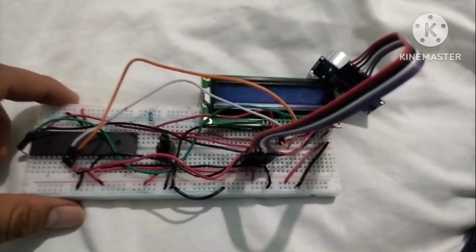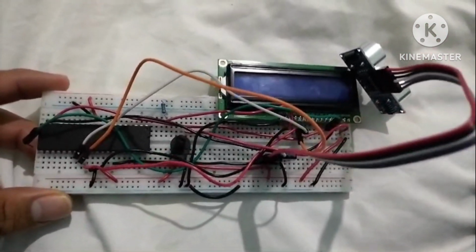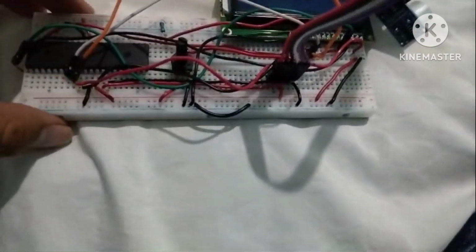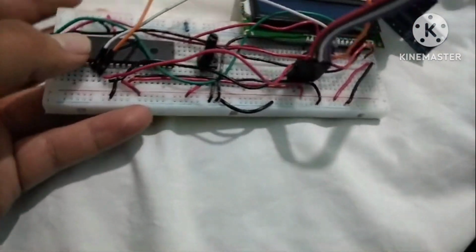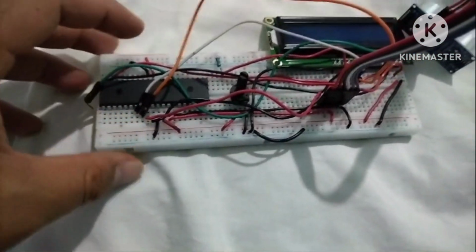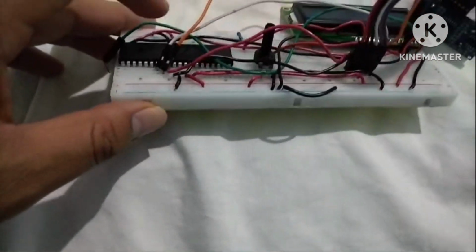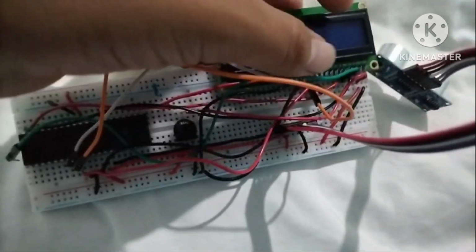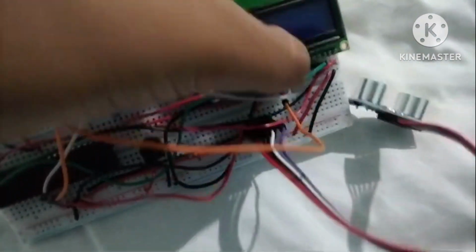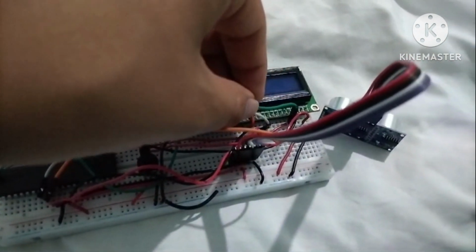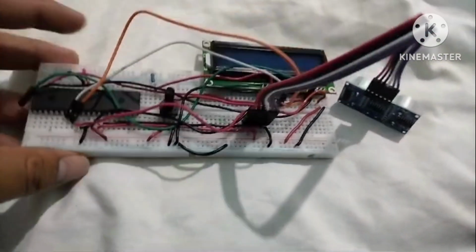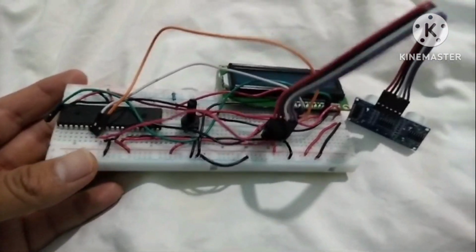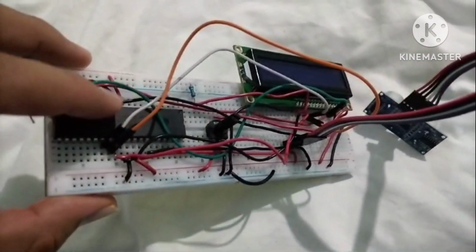My name is Jose, and I will present the connections. First, we need to ensure that pins 11 and 32 of the PIC are powered with their respective grounds. Next, we have to connect D4 to D7 from the LCD to the respective D4 to D7 pins of the microcontroller, that is this.